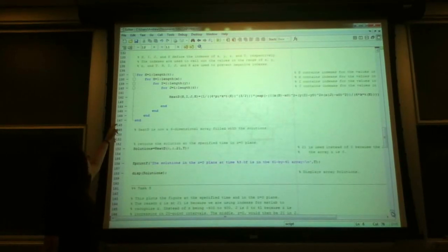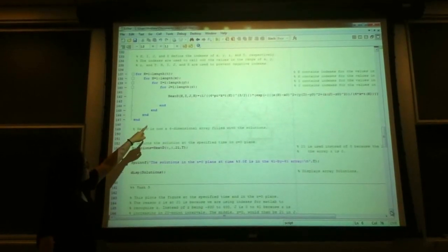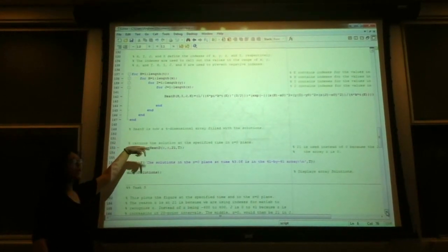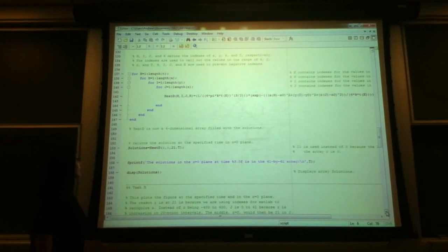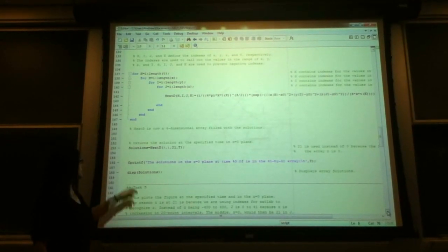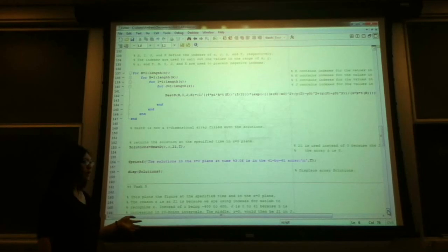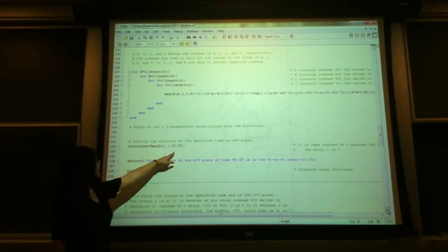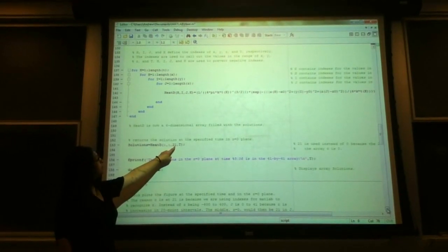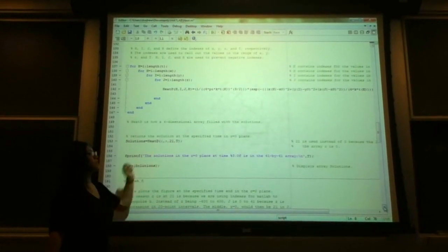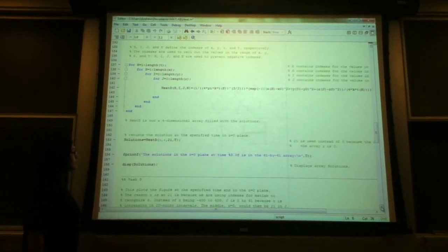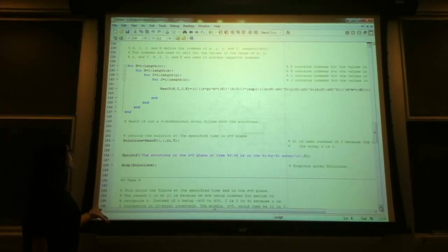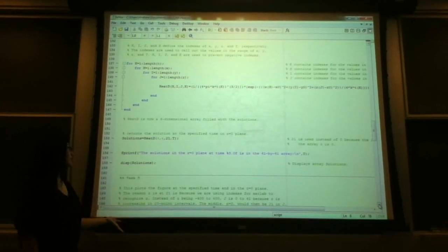So now we put the equation and we have our solution, and it fills up the heat D array, which is the 4-dimensional array. And we are asked to provide the solutions on the z equals 0 plane at time t. And this is 21 because the 21st variable value of the array z is actually 0.